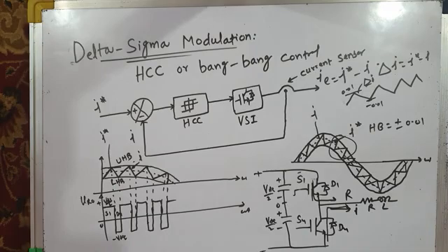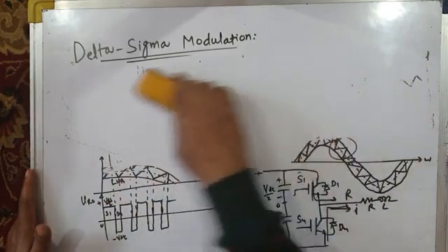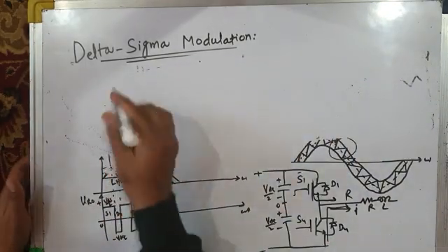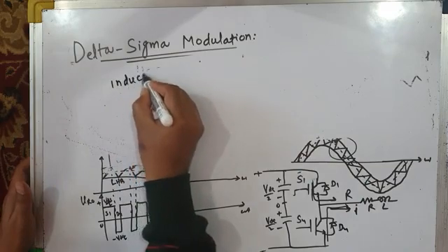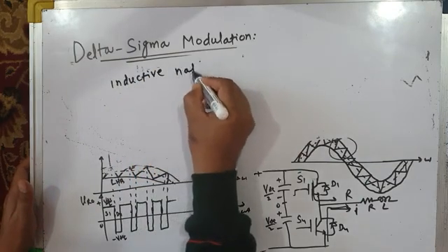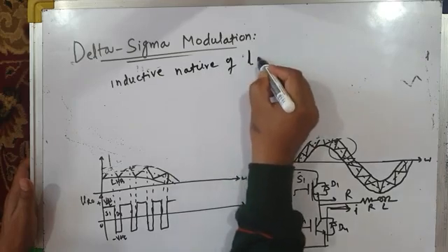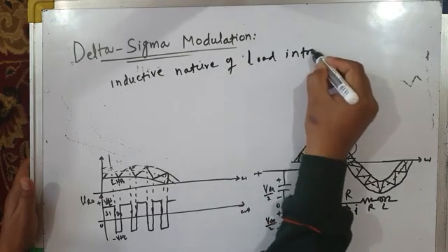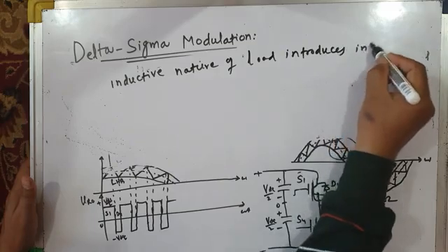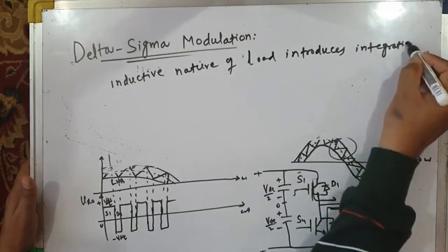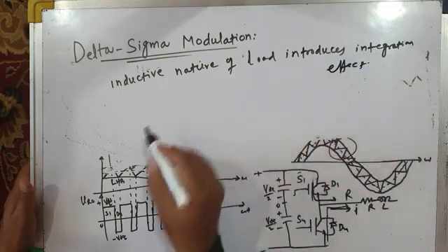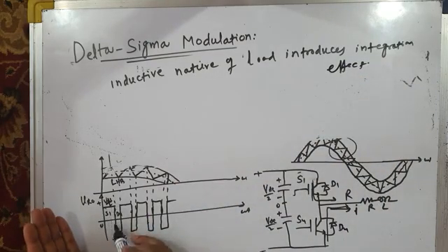Now, there is one very important characteristic of load. The load is inductive in nature. And inductive nature of load introduces integration effect. So I will write here. It's a very important point. Inductive nature of load introduces integration effect. Try to understand this point.